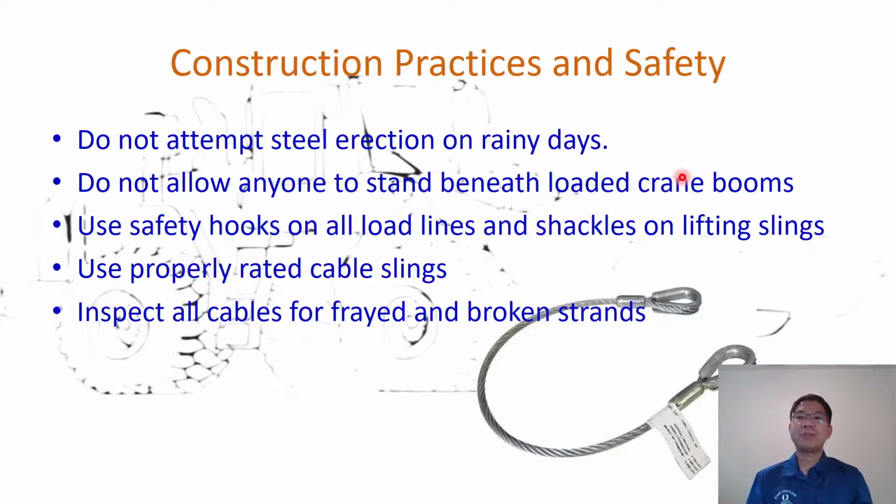thunderstorms, lightning, etc. Do not allow anyone to stand beneath a loaded crane boom, because the load may fall down, the structure can fall down, and it can be a disaster. Use safety hooks as you saw here on the load line, or shackles on the lifting sling. Use a properly rated cable sling, and inspect it, because sometimes it will wear and it can break and create an accident or incident. Inspect the cable for broken strands, and if anything is unusual, we have to change